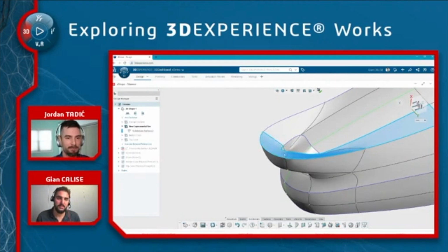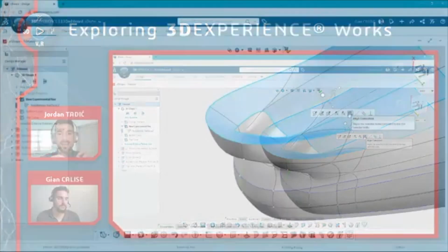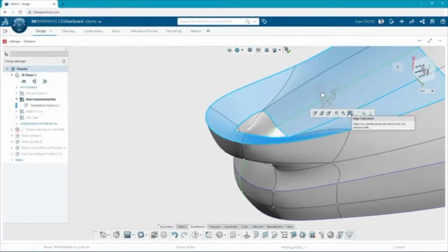Definitely. Nice. And if you want to do some tweaking, you could select all those faces and make them coplanar by making them coincident. And if you look at the other things on your toolbar right now, we can make edges collinear with one another. We can make them parallel, perpendicular. So there's more parametric controls to quickly and precisely align all these edges and entities and vertices, you name it. And with faces selected, it'll just average them out onto the same plane. So give that a shot.